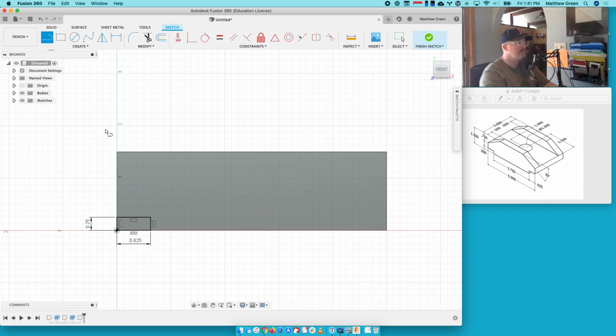All right, now I'm going to grab the line tool and start hovering over until I get close to the middle, and then watch what happens when I get to the middle. Bam. That little triangle means you're at the midpoint of a line segment. Cutting things in half is really common when you have a symmetrical design, so I'm essentially using this line to find the midline of this face.